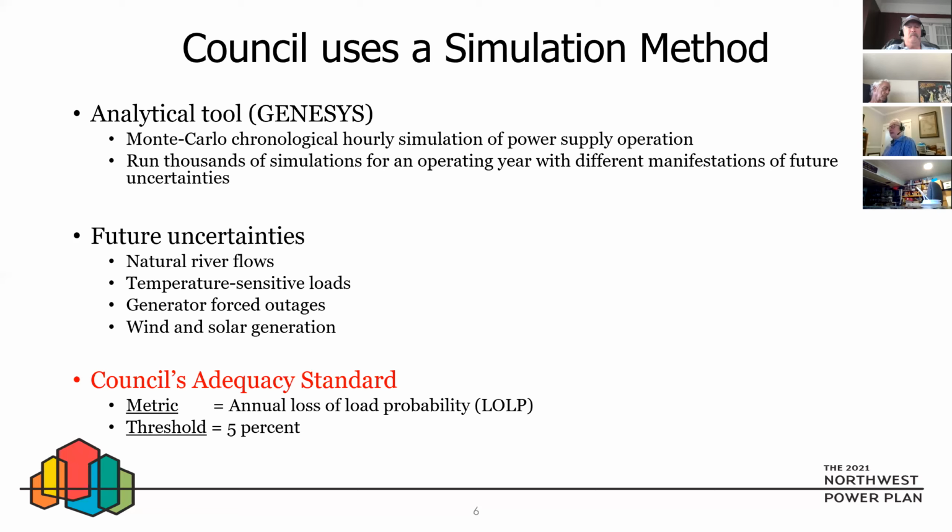Well, the way that they calculate the balance is that for hydro, they use the critical hydro generation, which is a 1 in 80 year event. The difference between critical hydro generation and average hydro generation is 4,000 megawatts. And so even if the load resource balance is negative, and it was starting to get negative in the mid to late 90s, you might still have an adequate supply because let's say you're 1,000 megawatts deficit. Well, shoot, you still have a pretty good chance of being okay because there's 4,000 megawatts more. If you were to get an average water year, you're in the clear. The problem was that the load resource balance was getting close to minus 4,000 megawatts by the end of the 90s.